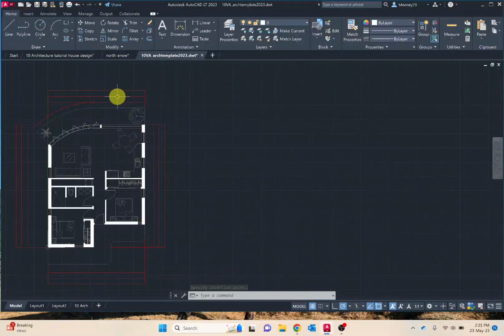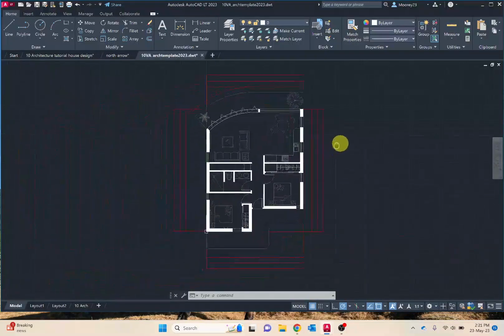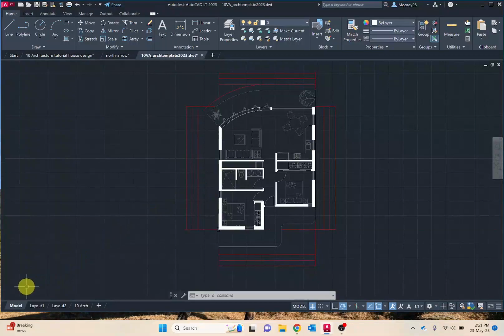Now, things you might have noticed is the dimensions have minimized. They haven't disappeared, they're still there. We just need to go through and do those dim styles once again. But getting our model ready for presentation, we're moving away from the model space. In the model space is where you go through and be applying all the modeling. Now we're looking at presenting it.